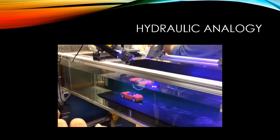So for this we are using this hydraulic analogy. The analogic method, which is used for qualitative and quantitative study of high speed flows, this particular hydraulic analogy is important. And also we can go for shallow water flow. Shallow water flow, especially for low speed flow, is suitable. So let us see the low speed flow model of simulation in a water flow tunnel,